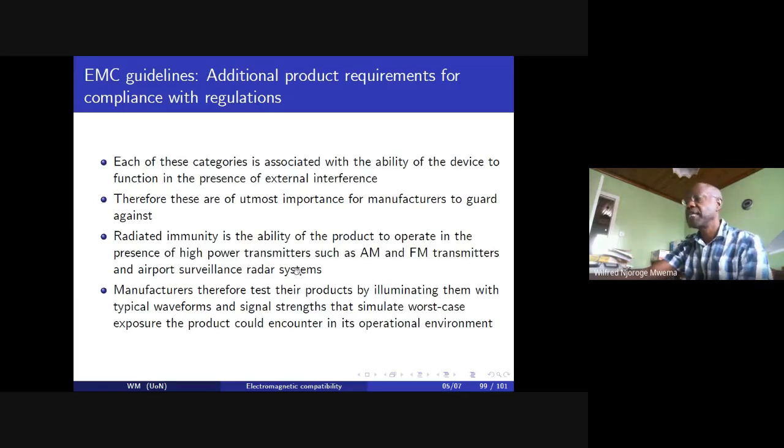If you are dealing with satellites, the temperatures up there will be very high during the day and very, very low, below freezing, in the night. And therefore, you want to have components that can operate in those wide ranges. So the same thing, you'll be facing the solar radiation when you're up there, and therefore will it interfere with the operation of your system or not?